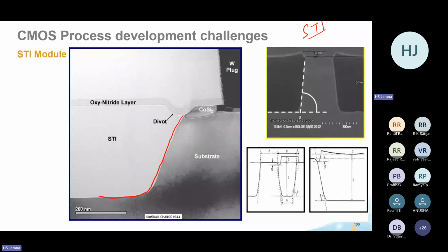These are real pictures from our SCL fab, and these are cross section images. As you know, there are skilled people who work on these TEM and SEM, because these are cross section images and you have to cut the wafer at a particular angle. So you have to prepare the sample, then only you can take an image. They should have some idea where that well is, and normally they will cut at 5 or 6 places, and maybe one of the places will give the correct geometry.